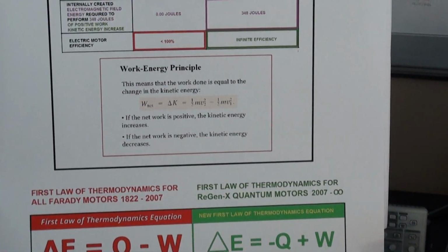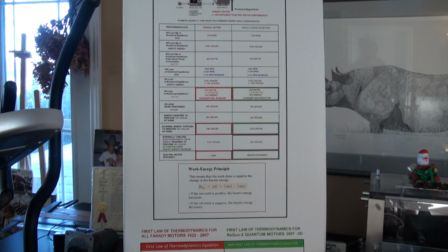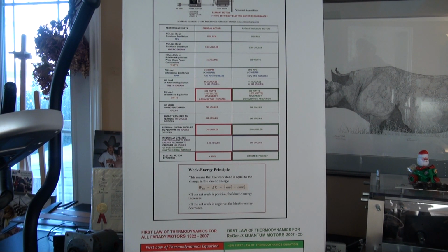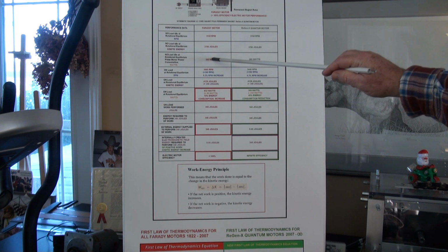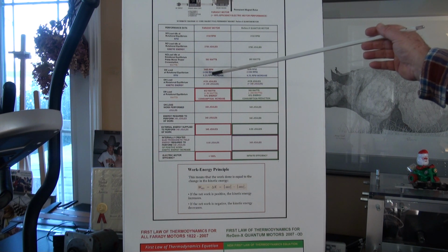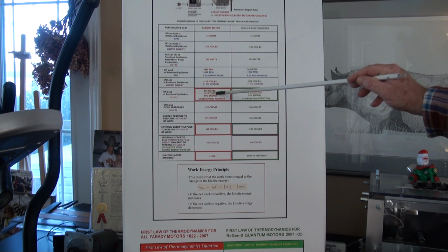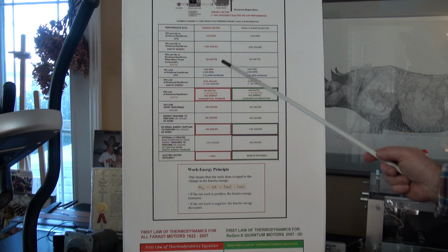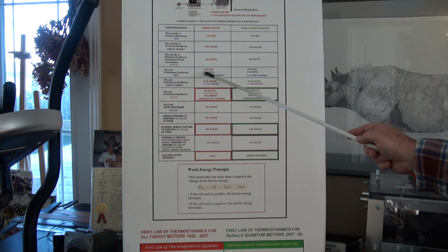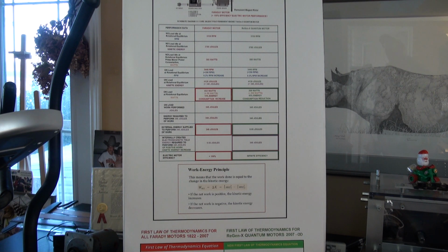So with regards to the data, it's pretty hard to see the table, but rough numbers, the Tesla motor was using about 655 watts at idle, and in order to increase the RPM by 290 RPM, we had to put in an additional 88 watts to the motor, and we got the speed up. We increased the speed by 290 RPM, and we increased the input power consumption to the motor by 88 watts.